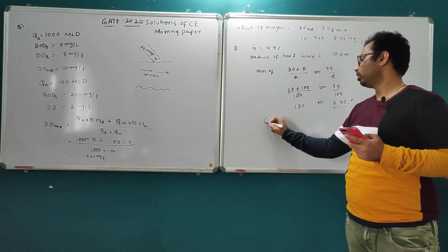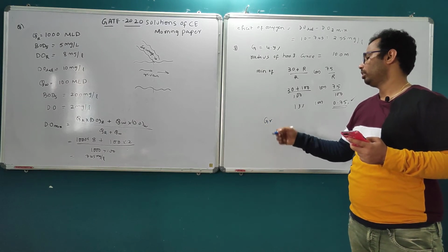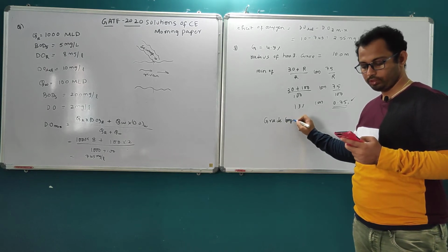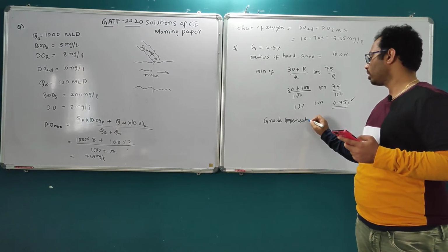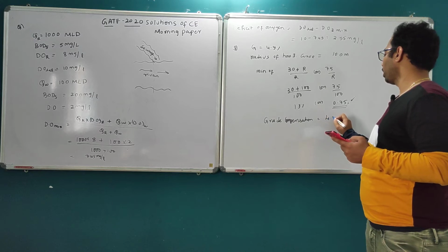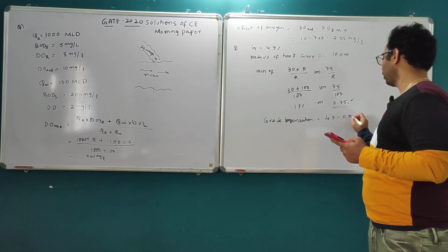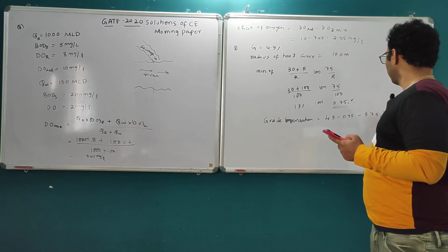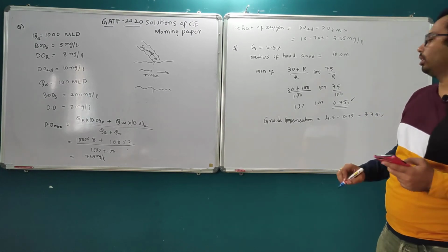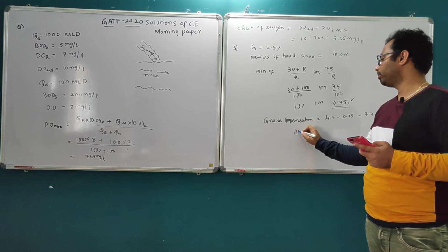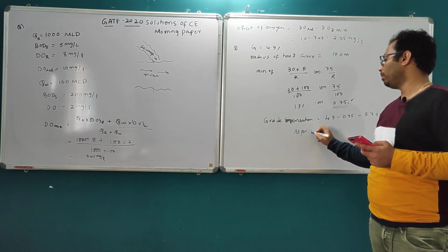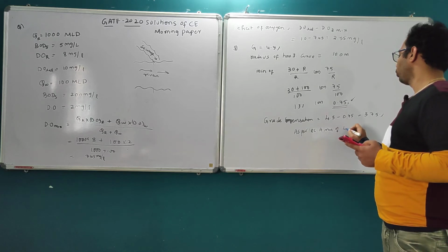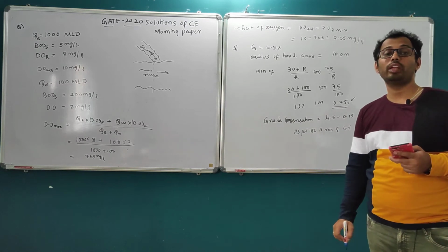So grade compensation after grade compensation is equal to 4.5 minus 0.75, that is equal to 3.75. But as per IRC, a minimum gradient of 4%. It cannot be eased more than 4%.